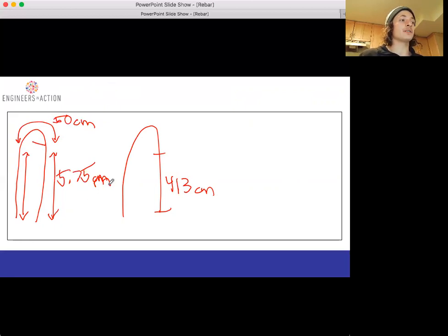So in order to do this most efficiently, it's good to draw up a cut sheet for all of your rebar calculations in your tower and anchor suspenders, and try to make the cuts as efficient as possible. However, be careful, because the most efficient cutting scheme would then need to be followed in country, because if you order for the most efficient scheme, there is potential for running out of material if that's not actually followed.